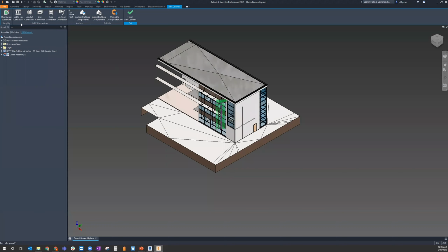Inside of there, depending on what you are going to be publishing, whether it's cable tray connectors or maybe you're creating some tube and pipe connectors, you're going to want to use some of your MEP connectors and then go through some of the authoring components for the building components that you're making, whether it's some AC units or anything else that's going to be utilized within BIM or inside of Revit projects. I would go through and update all these properties as much as you can. And then you would go through this export building components, and it's going to allow you to determine what type of file type you want to export to, whether it be an RFA file for Revit files or, like I did say, .adsk files.